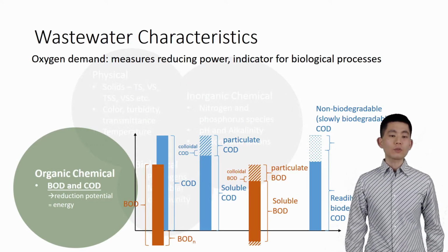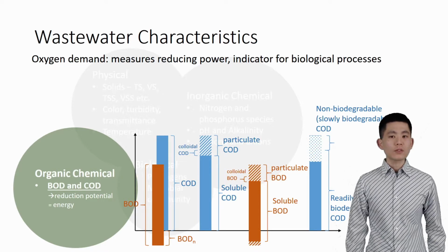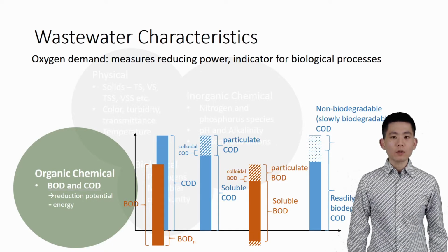This figure shows the relationship between COD and BOD. The carbonaceous COD is higher than the carbonaceous BOD, as some organic carbon that can be oxidized chemically are recalcitrant to biological oxidation.